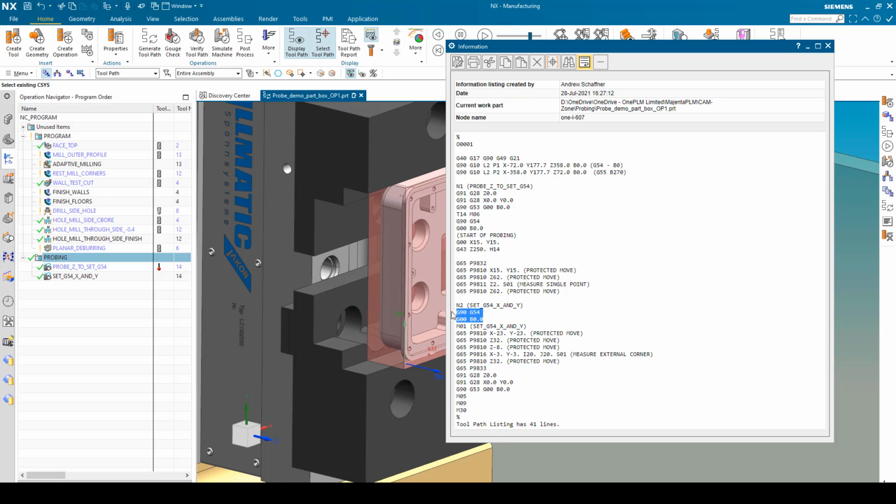But what it does do, it updates the work offset and the position so that it's updating anything which took place above it, and then quite simply goes to another protected position, goes down, Z minus 8, which is obviously, we know our surface is at Z plus 2, we asked to go to 10 below that top surface, so it's going to go to Z minus 8, does a probing move in two points, goes to protected position, and then goes and turns the probe off.